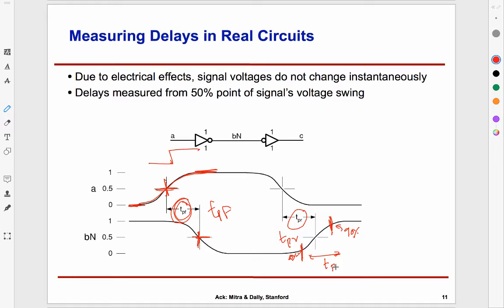So that's one issue. Those of you who do circuits will probably study it later. The other issue, which is a related one, is that when there is a sharp change in current, it generates the same noise I was just talking about. That noise can then be emanated into the air. And so you see what is called electromagnetic interference, which means that when your device is operating, it generates all sorts of radio waves and causes interference around it. This is why, among other reasons, during landing and takeoff they make you shut off your electronic devices: these devices are usually not very well designed, and they generate radio waves around them because of this effect, which causes interference to avionic systems. So that's another reason. So fast is not always good. I guess that's the moral of the story. You want them fast enough, but no faster.